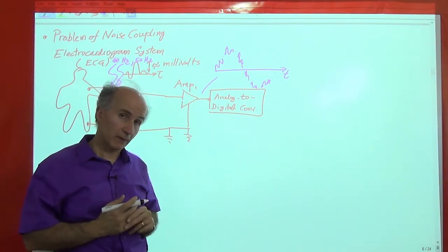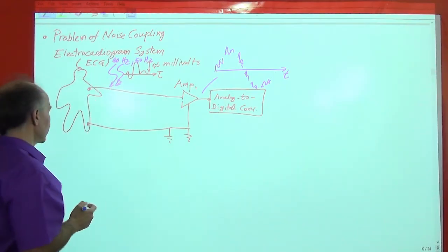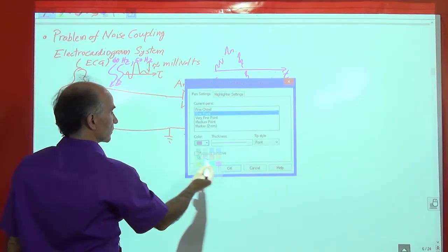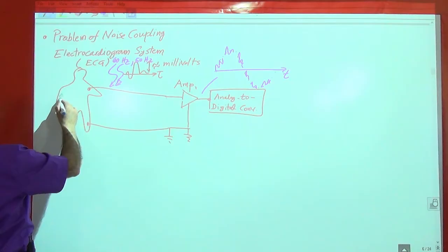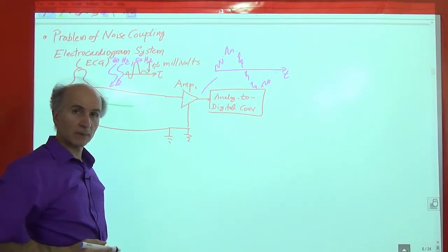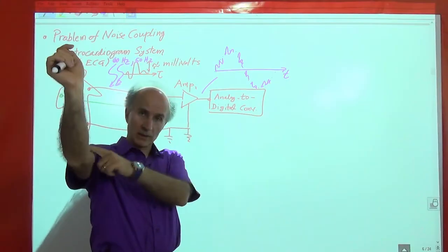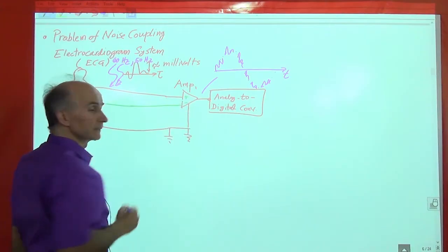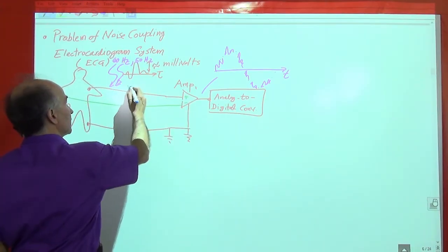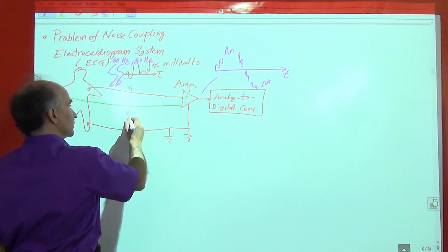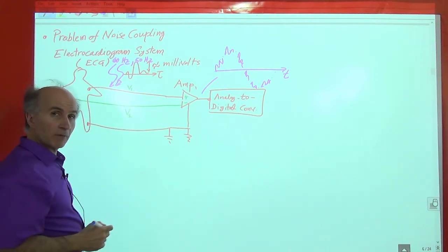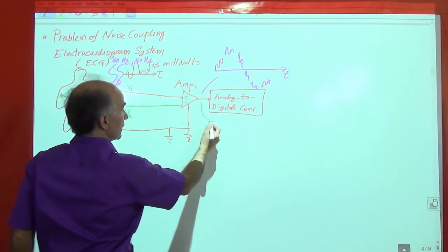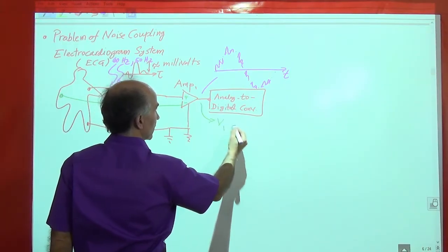All right, so what we do in practice is the following. We will attach one more line to the patient. So let me change that to green. So to the other arm of the patient, we attach another electrode. Okay, so one on this arm, one on this arm. And we give both of these to an amplifier that has two inputs. So if you call this V1 and we call this V2, this amplifier is like an op amp, right? Not quite an op amp, but like an op amp. It subtracts these two, so here it will generate V1 minus V2.